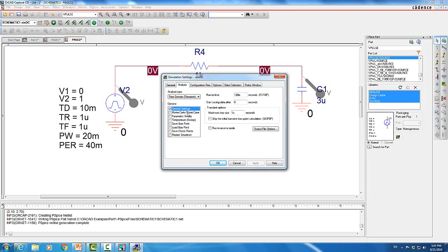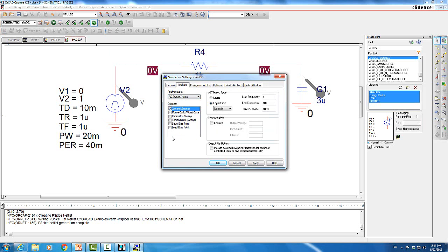That is extremely important. Another one is temperature sweep. Many electronic circuits will vary with temperature. You can do that. There is another one in the AC sweep called noise. So we need to have noise analysis to run the frequency. So you can do noise analysis, and to do noise analysis you can come here and also run a noise sweep. Now those things you can also learn when you get to learn advanced topics in electrical engineering.